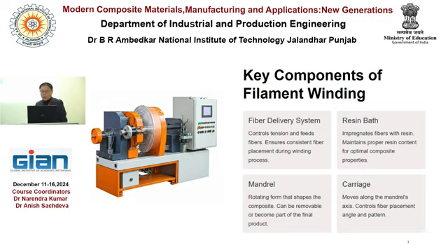The filament winding patterns: three typical patterns are used. For a cylindrical mandrel, helical winding is used, because some fixed winding angle is needed. Or hoop winding, which is like a waist belt. And if it is not a cylindrical shape but a spherical shape, something like that, polar winding technique is needed. Those can be controlled from the control panel.